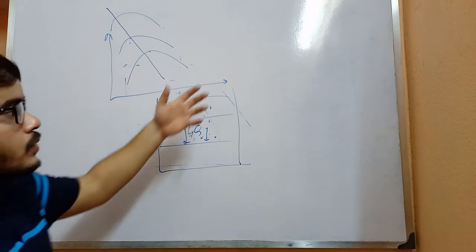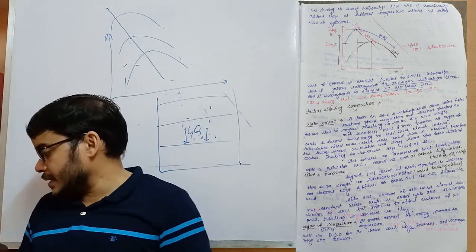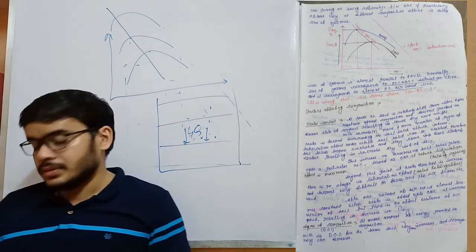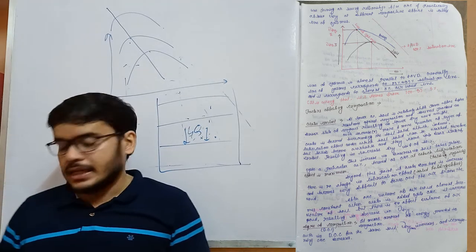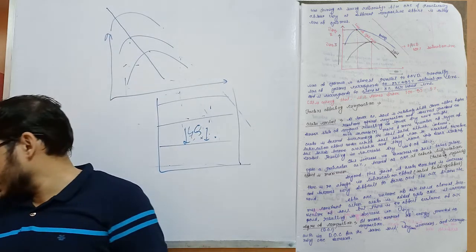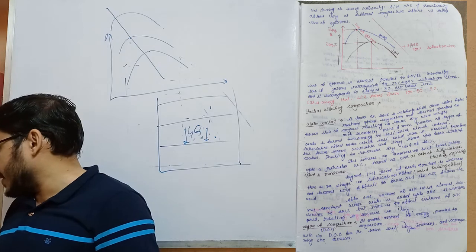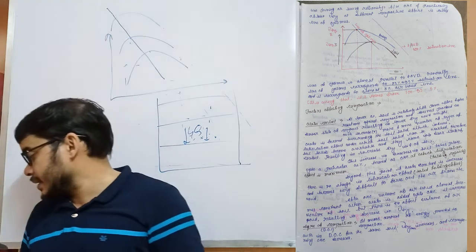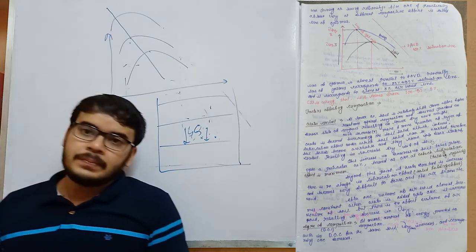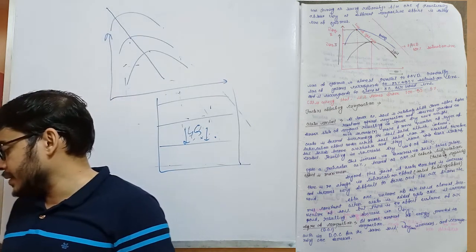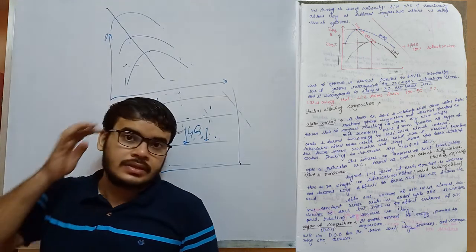Now again the note is here: the line of optimum is almost parallel to ZAVL, that means the zero air void line. Generally the line of optimum corresponds to the 85% to 95% saturation line, and it corresponds to almost the 5% air void line. Complete the note. And now, water content.